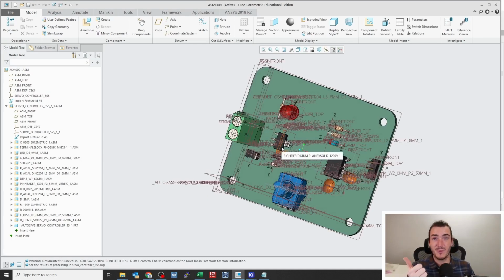And so there you have it. We were able to import CAD from online to using KiCAD, and we were able to export a file to be used in 3D modeling. I imported this as an assembly. You may have better luck just baking it as a single part, but in any case, this is now ready for anything you want to do with it, like 3D modeling for enclosures or printing a test fit kind of resin print that you can hold or offer up into some enclosure and make sure everything lines up.